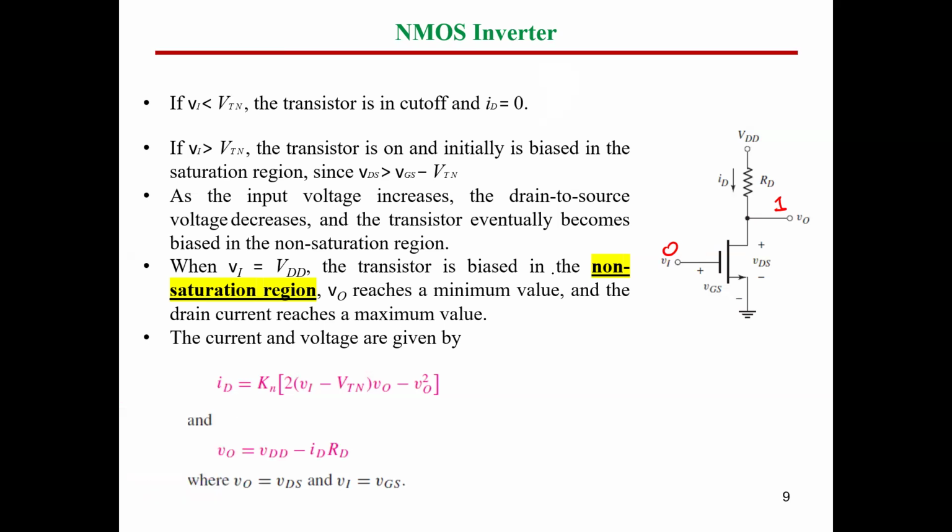Now, if you have active high here, this switch will be turned on, so V out will be the same as VDS, and VDS is a relatively small value in linear mode, which means it's going to be active low. So as you can see, we could invert the outputs. The 0 logic became 1, and the 1 logic became 0. So as you can see, guys, this is an inverter logic gate.